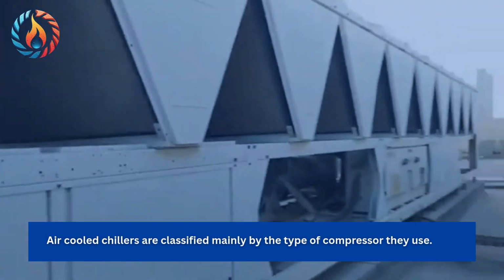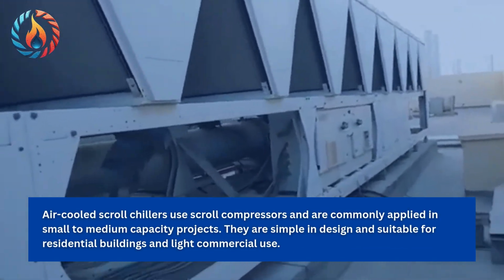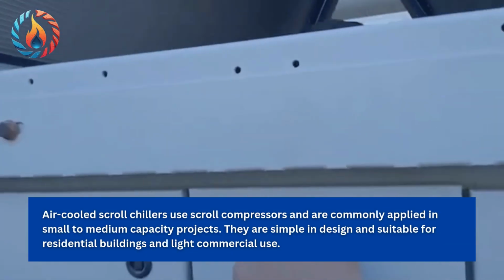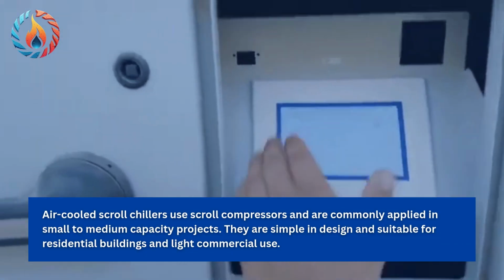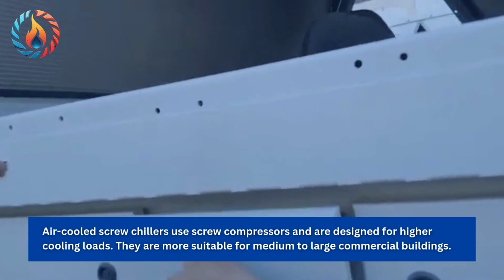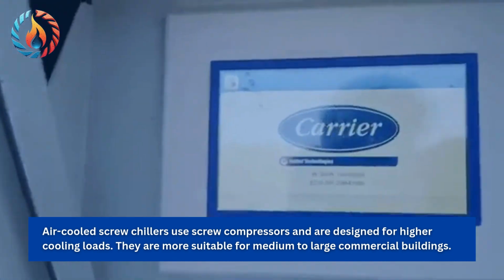Air-cooled chillers are classified mainly by the type of compressor they use. Air-cooled scroll chillers use scroll compressors and are commonly applied in small to medium capacity projects. They are simple in design and suitable for residential buildings and light commercial use. Air-cooled screw chillers use screw compressors and are designed for higher cooling loads. They are more suitable for medium to large commercial buildings.